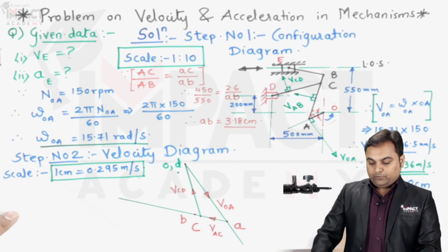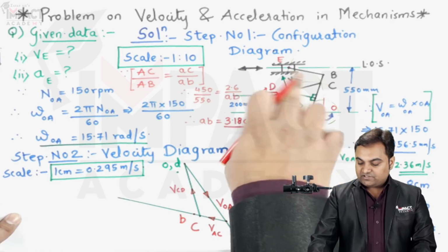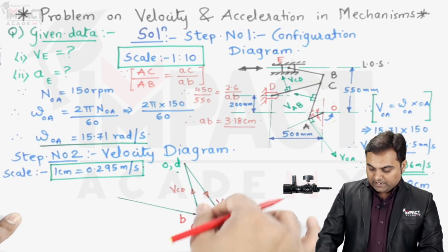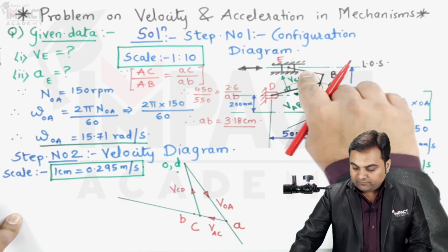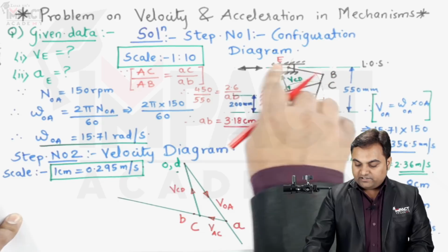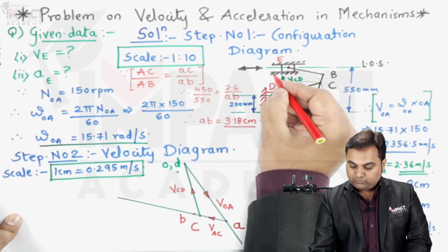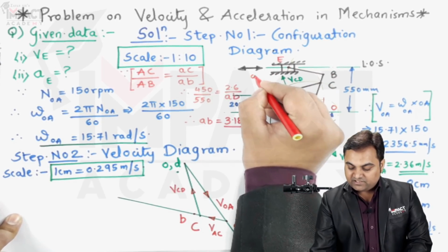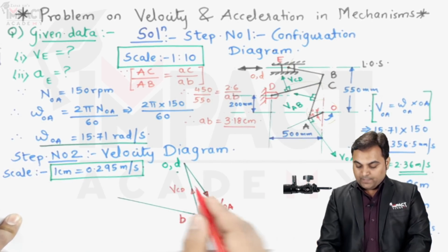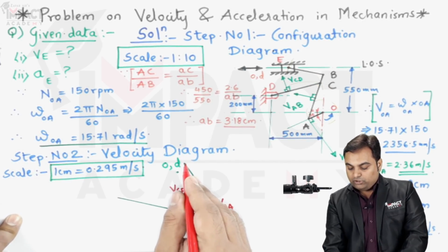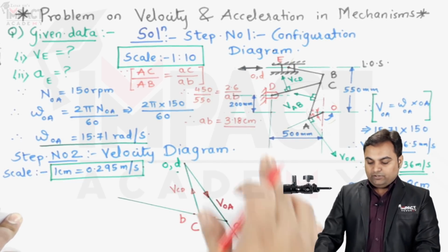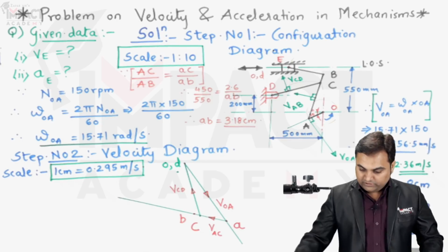Now after getting point B, the link which is left is link BE, and obviously the velocity vector would be upward, because when the velocity vector of BE would be upward, after that the slider is reciprocating with respect to the fixed guides, and fixed guides are denoted by O and D. These are the fixed points. So from O and D we are going to draw a light horizontal line, and the intersection would give us the velocity of this slider. So first of all I'll explain.